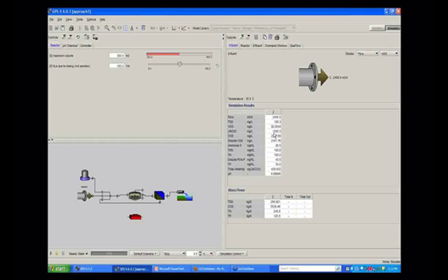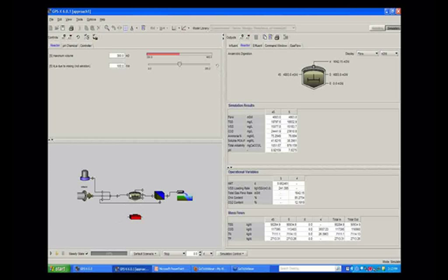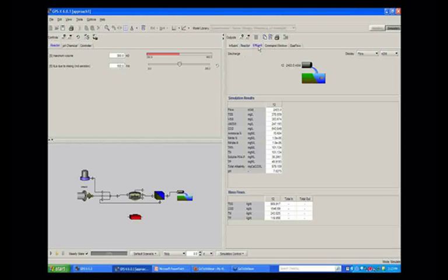If we look into the reactor, which is this reactor here, you can see the TSS concentration which is built up in the reactor is in the range of 19,000 milligram per liter. You can also see that the total gas production rate is 1,642 meter cube per day for this particular configuration with a methane content of 85%. If we look at the effluent characteristics, we can see that the TSS concentration going out in the effluent is 378, VSS concentration of 303, and BOD of 247.